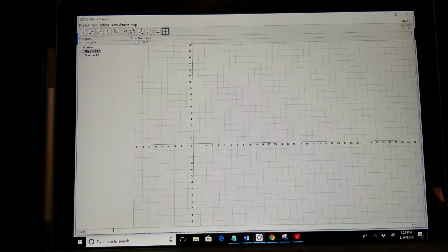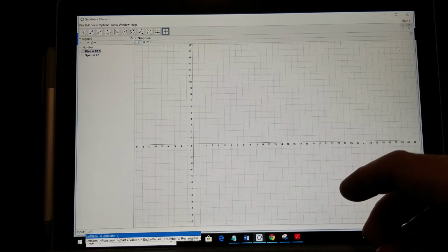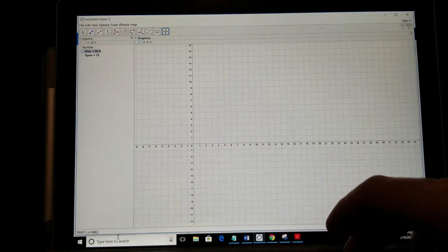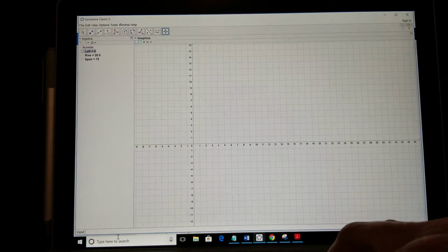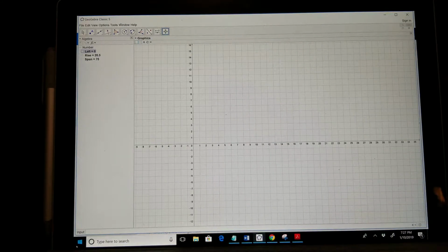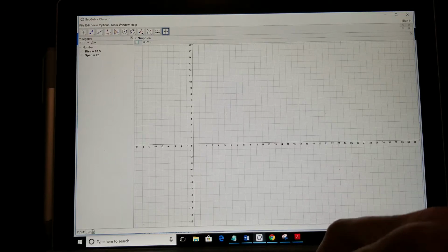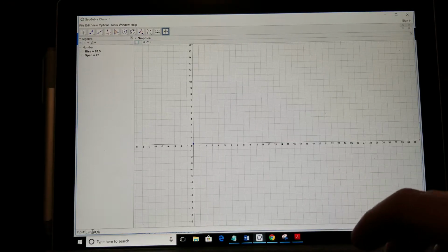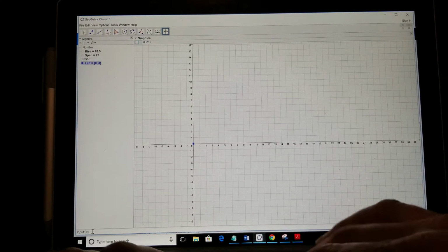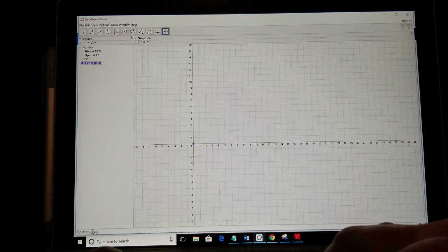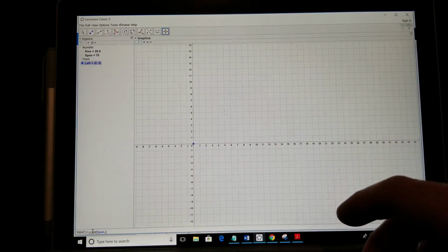And then we will drop down the left point. Remember, if it's a Cartesian point, you have to start with a capital letter, and that will be at 0, 0. And the right, oops, I made a mistake there. The left Cartesian coordinate is left parenthesis 0, 0. And the right Cartesian coordinate, capital R, will be left parenthesis span, 0.